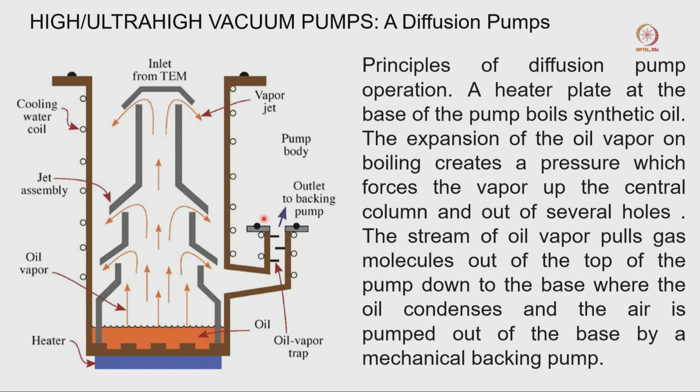What is the next pump? As we mentioned, the next pump is the diffusion pump, or it is called the oil diffusion pump. Generally this oil diffusion pump gives us a very high vacuum. How is this oil diffusion pump working? You can see there is a heater connected, and there will be oil inside that pump at the bottom of the pump.